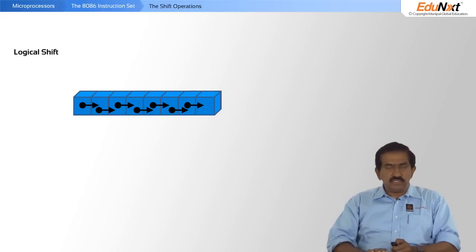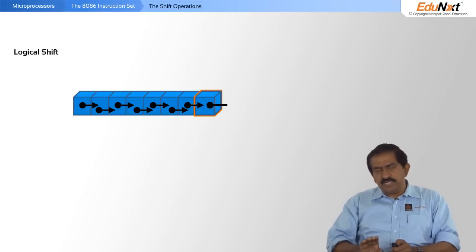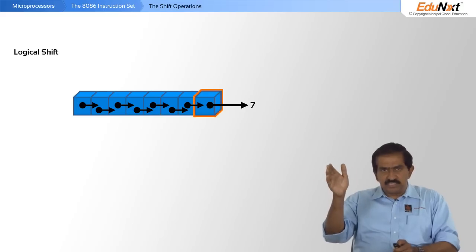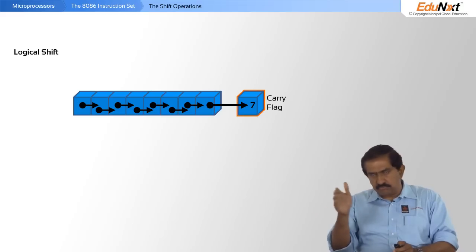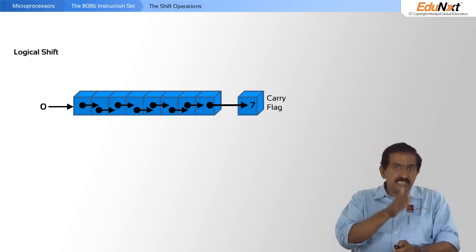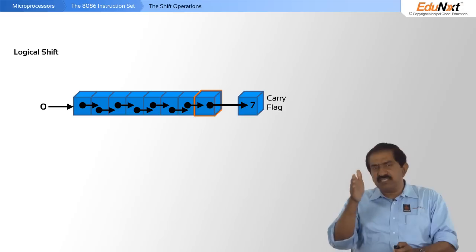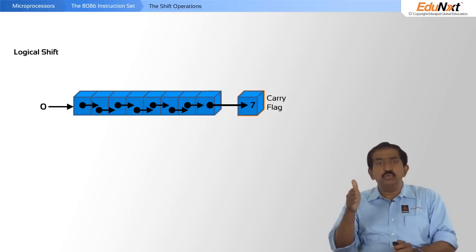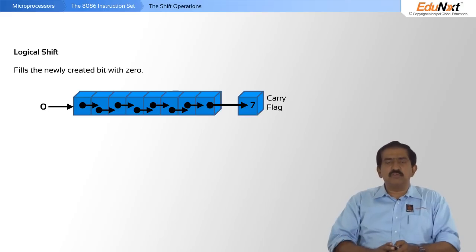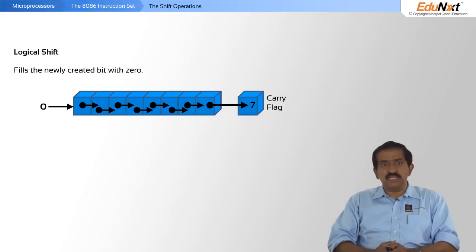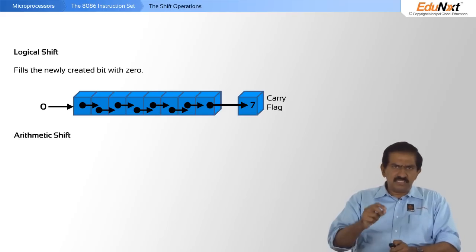The logical shift moves bit 7, the highest bit, B7, into the carry. The carry flag is now the bit 7. Bit 0 of the value is filled with zeros. So B0 becomes 0. B7 is shifted into the carry flag. And you can use this to determine what bit 7 of every byte in a memory location is, if your program so decided. The arithmetic shift is a little different.